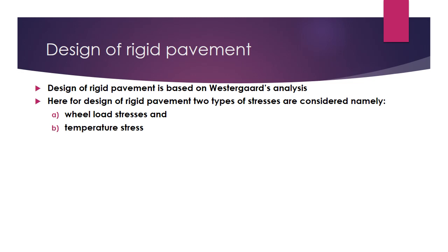In Westergaard's analysis, he took two types of stresses, namely wheel load stresses, which are due to the stresses imparted by the various wheel loads, and another one is temperature stresses. Now, wheel load stresses are due to the loading of the various vehicles, which is transferred through the wheels of a particular vehicle.